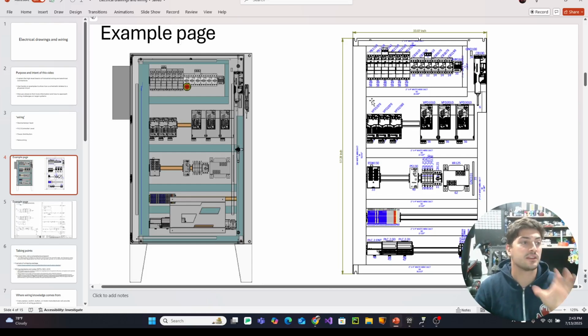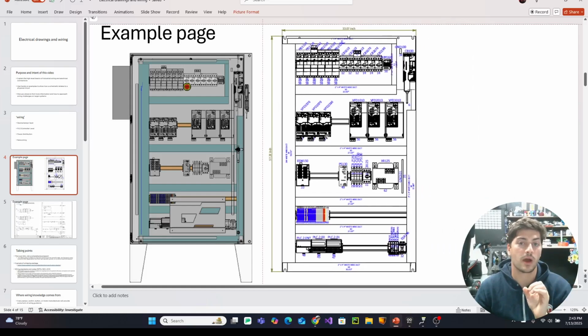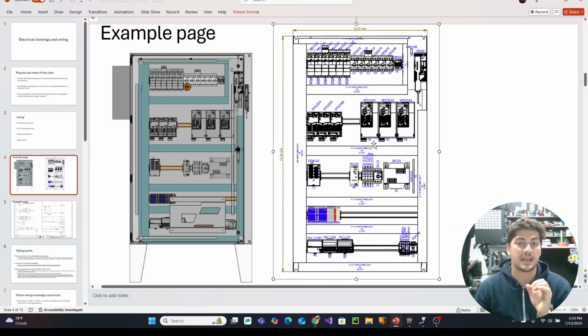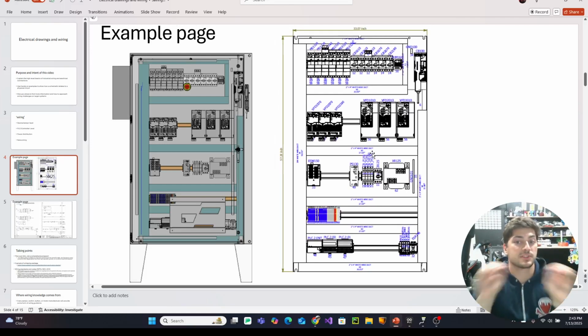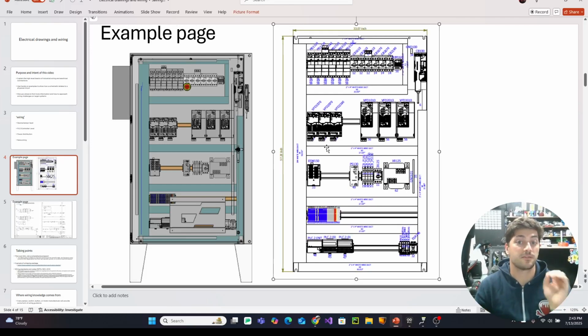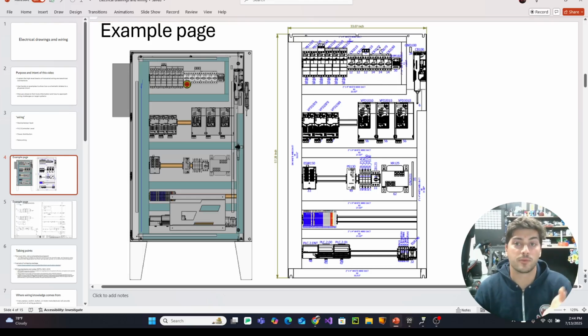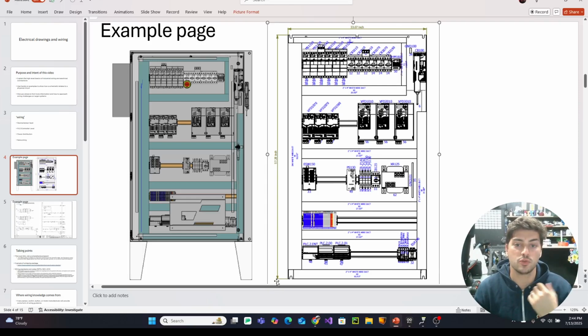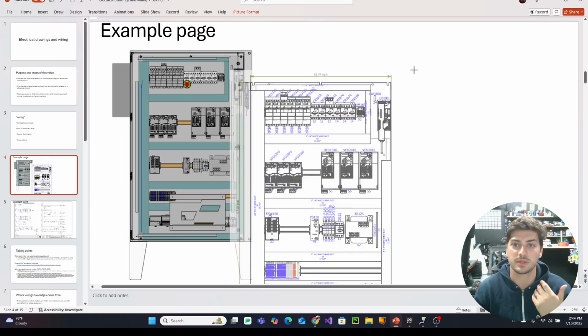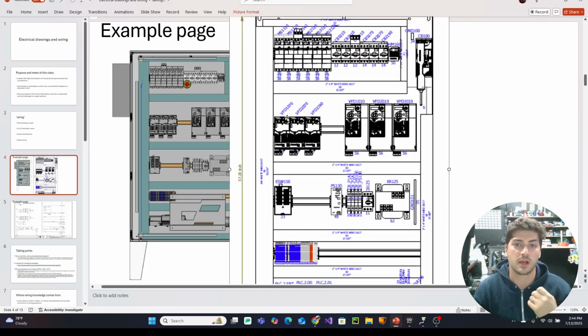And then on the right, you have what's called the wireframe, which is usually a still precise, but slightly less precise physical rendering of the panel. But everything would be labeled with however it's getting called out in the drawing. These are basically the same control cabinet, but on the right there's a lot of small blue text that's kind of hard to read, but there are a lot of blue labels calling these VFDs out as VFD 1070, 2070, 2190.